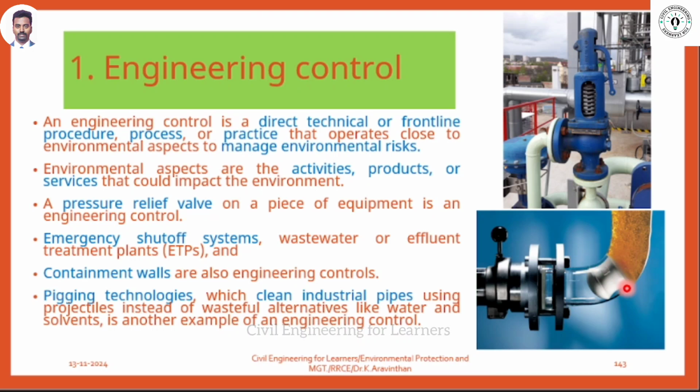The oil supplying industry uses this technology in order to push this highly viscous fluid. If it is stuck somewhere, can you see this? Some force is pushing from one side. So this is pigging technology. This is used in cleaning industrial pipes wherever it is stuck.